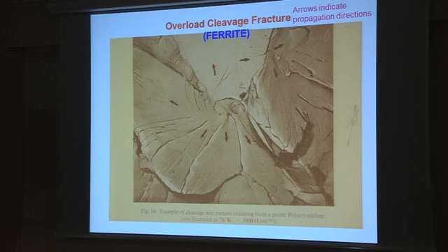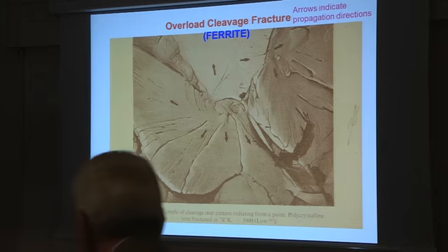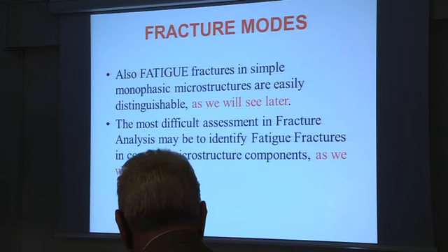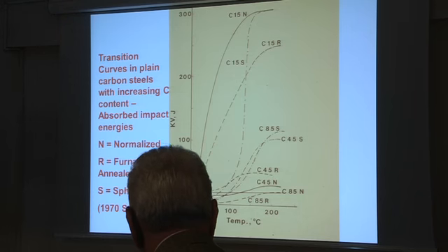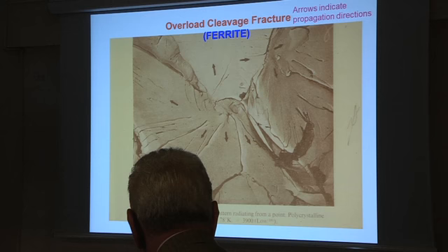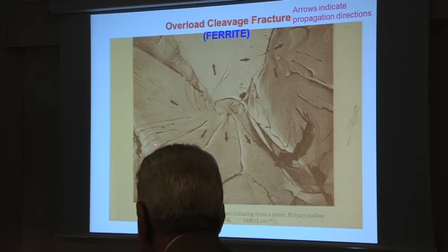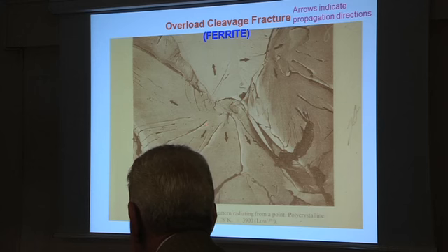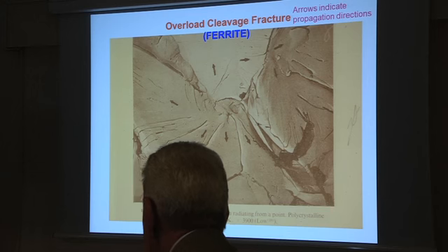And then you have little differences in the position in space, and the last fracture is a shear fracture that breaks the remaining ligament, the little remaining ligament between plane and plane.